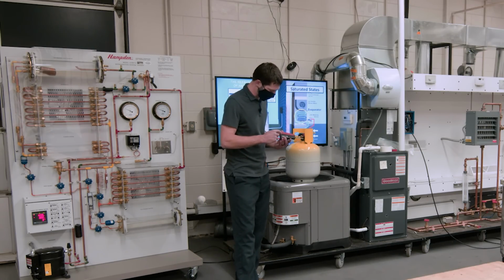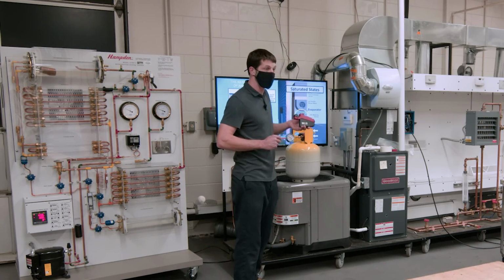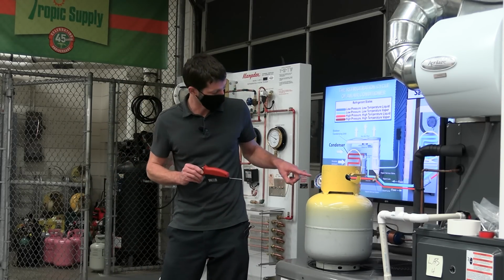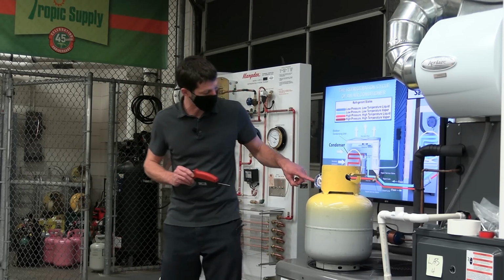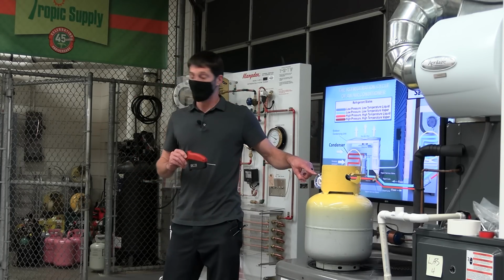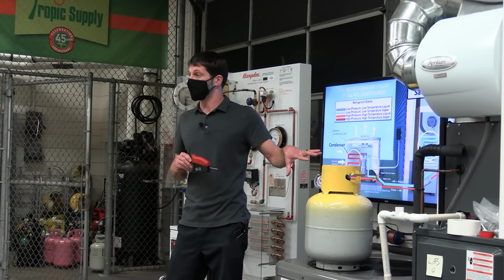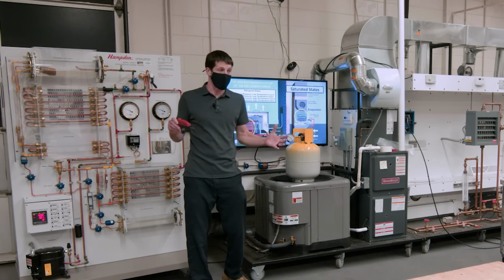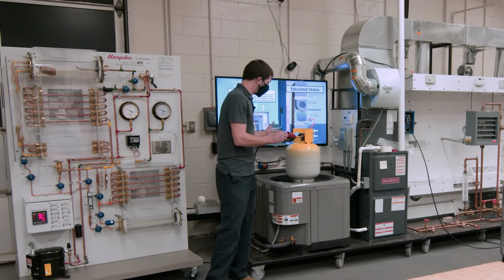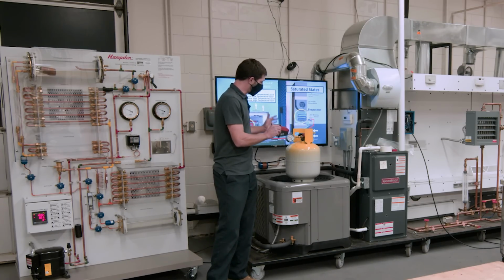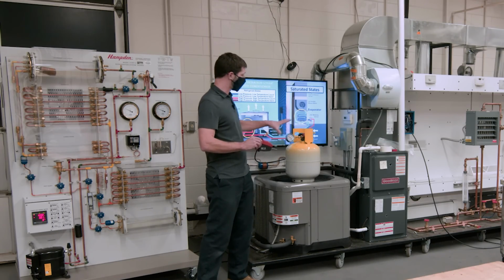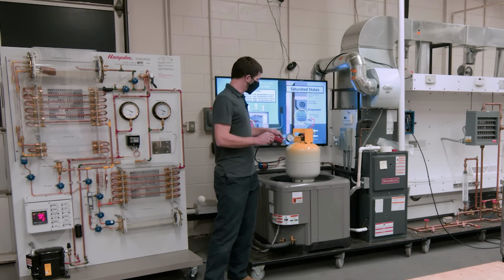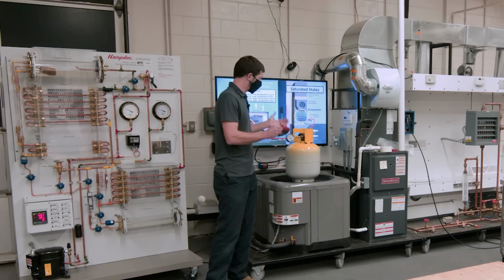So this temperature meter right here says it's 70 degrees inside. That bottle should be at 70 degrees saturated temperature for R410A. It has too high of a pressure. I would not reuse that refrigerant, and I can confirm that because this was in this room for several hours before we even got here, and so it was at a steady temperature. So that's how you check a recovery bottle in case you don't know what refrigerant's in it, and to tell if it's contaminated with air.